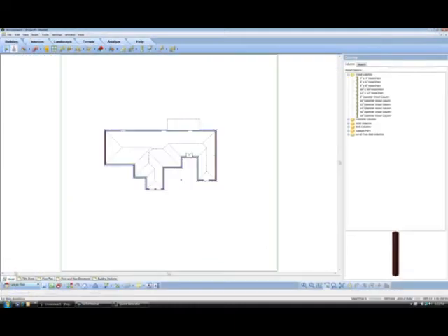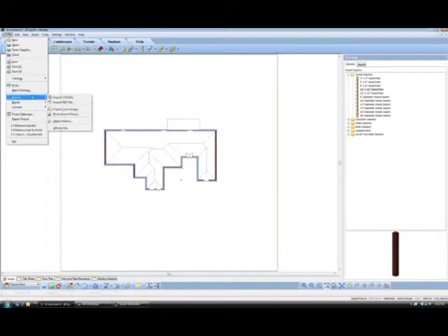If you're in the model view, you can bring in a DWG file for 2 different reasons. I can import an AutoCAD file because it's a 3D block, piece of furniture, a cabinet, something I want to use again with my 3D models that I'm developing in Envisioneer. And you do that through File, Import, Object Wizard. Or if I'm bringing in an AutoCAD file that I originally started as a floor plan, and I just want to trace over top of it to create a 3D model, File, Import, Import a CAD file. It'll come in as a 2D file, and you can trace over top of it, much the same as what we showed when importing a PDF.